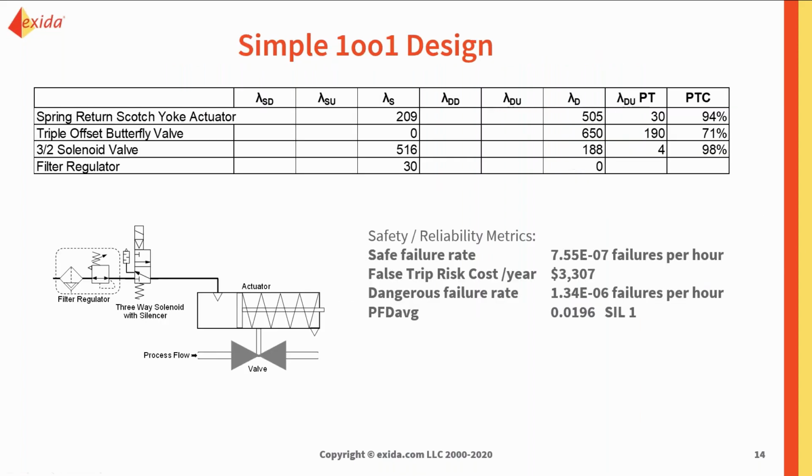So let's take a closer look at each one of these 4 designs. The first one being the simplest of them all, our simple 1 out of 1 design. We have just our spring return actuator on a triple offset butterfly valve, 3-way solenoid with our filter regulator.